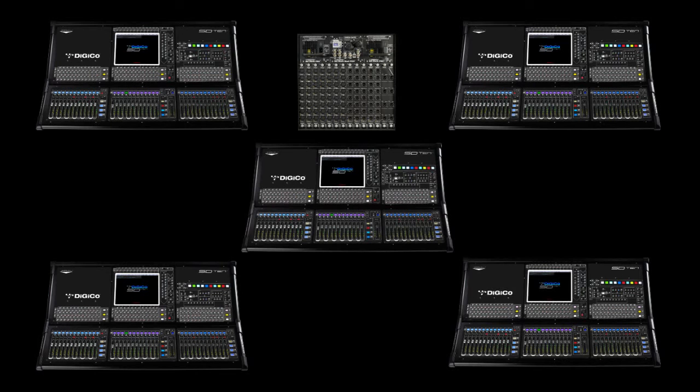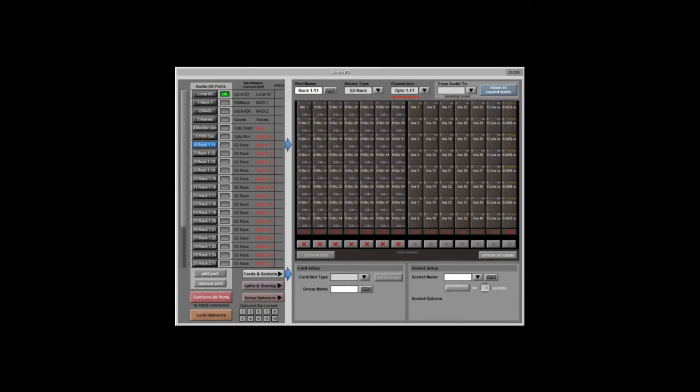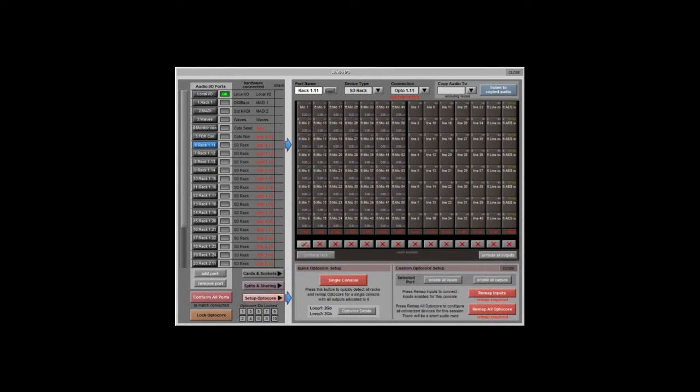2. 5 redundant consoles can share all input from the stage racks, and outputs on the system can be assigned in blocks of 8. Taking a standard front-of-house and monitoring system as an example, a single rack can provide 56 inputs to both consoles, with 40 of the outputs assigned to the monitor console and 16 used by front-of-house for feeds back to the stage.